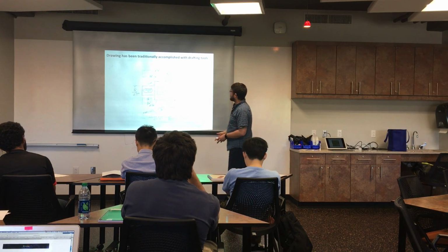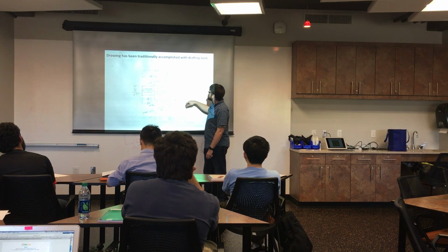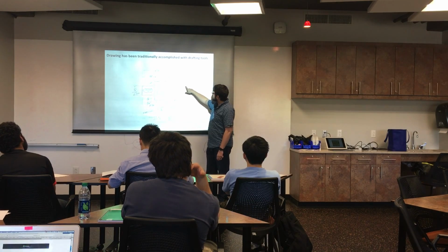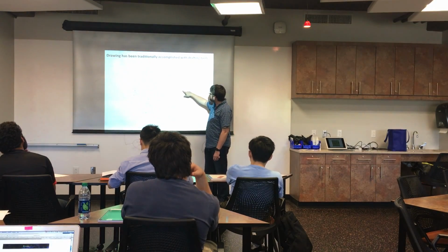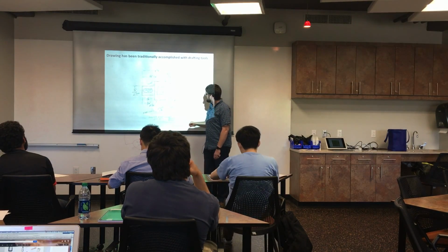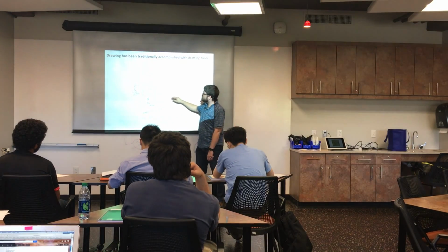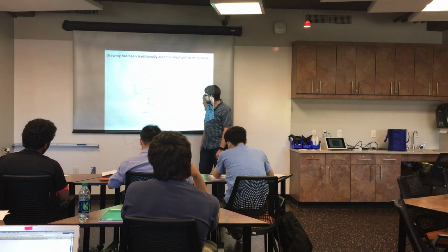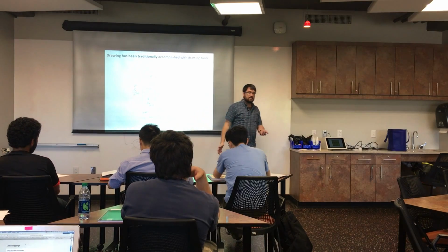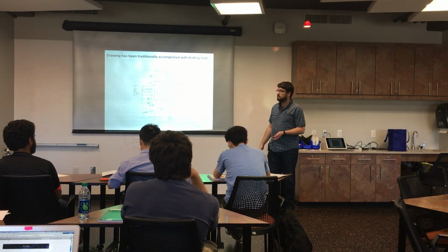So there are things in here like some dimensions. Here they say this is a 5/16 screw, 1 inch deep. There's a center line here, so we know that that's the center of the part, and all dimensions can be relative to that. So it's not bad, and it's something that would take you 10, 15 minutes to do.